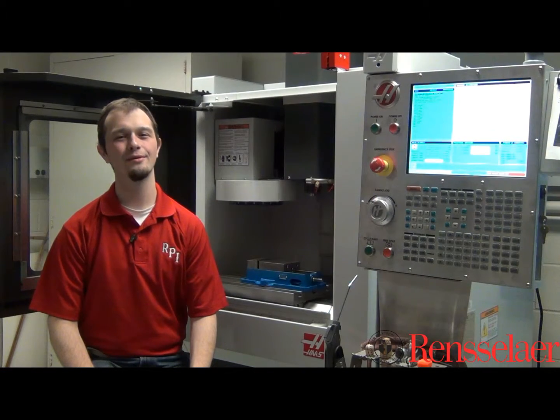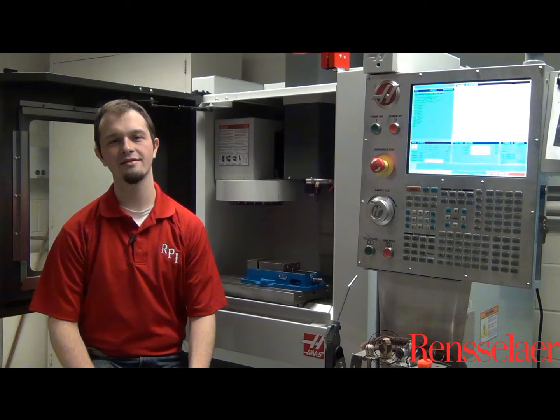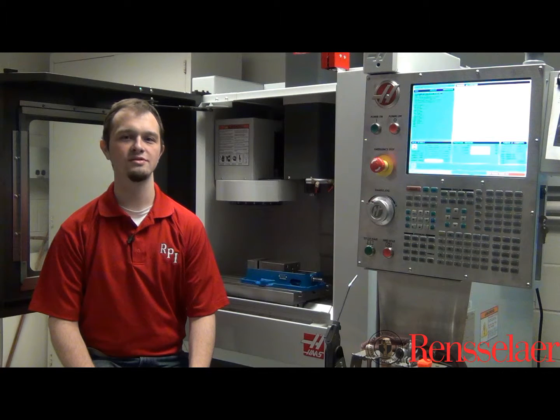The final difference that we observe between micro and macro-scale machining is the material removal mechanism. Typically in macro machining, all the chips are produced through a shearing process. However, at the micromachining level, we see both plowing and shearing occurring. Plowing occurs when we cut below the minimum chip thickness, and instead of having the material flow up the rake face and shear off the part, we push it, which results in a higher specific cutting energy, generally poor surface finish, and an increase in tool wear, which we'll discuss later in the lab module.